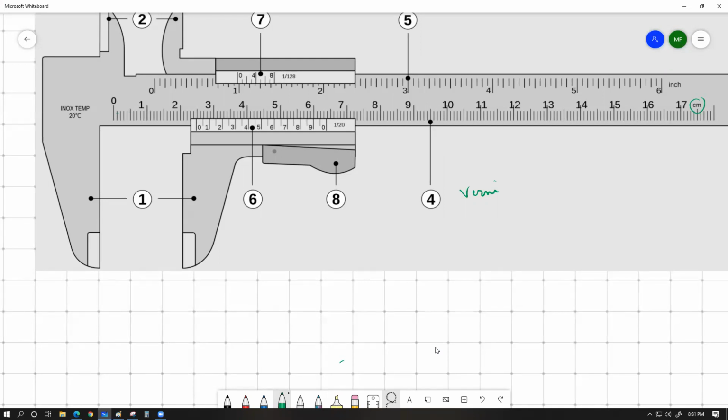For example, for a meter rule, the step size is exactly 1 millimeter. A meter rule can precisely measure between every millimeter. So 10.1 centimeter, 10.2 centimeter, 10.3 centimeters. So every 0.1 centimeter, which is essentially 1 millimeter, can be measured by a meter rule properly. So 1 millimeter is the stepping size of the meter rule. The Vernier scale has something of that sort: the smallest increment that a Vernier caliper can handle. That is called the Vernier constant.